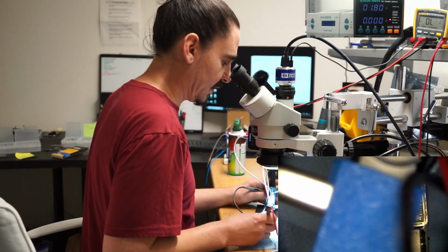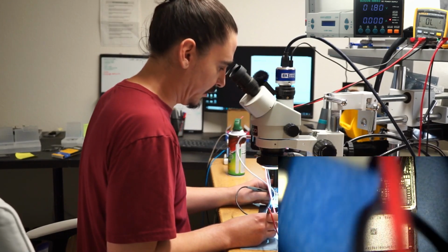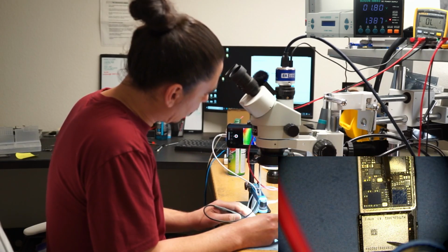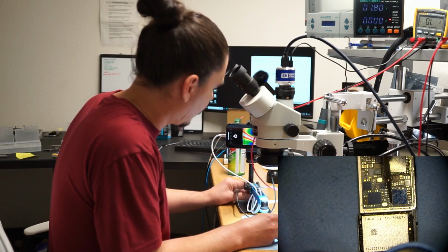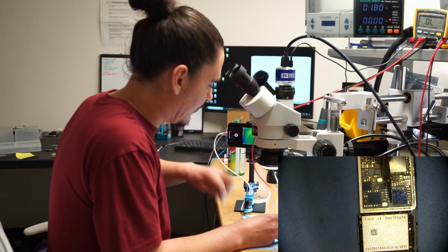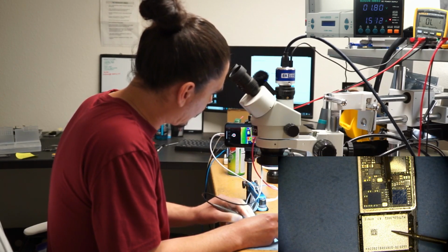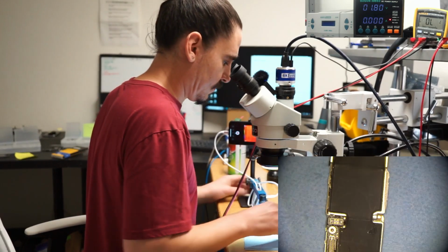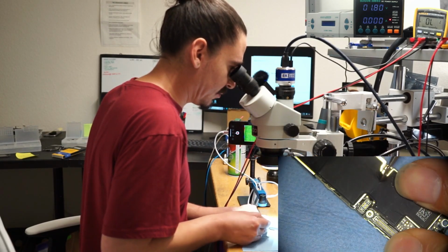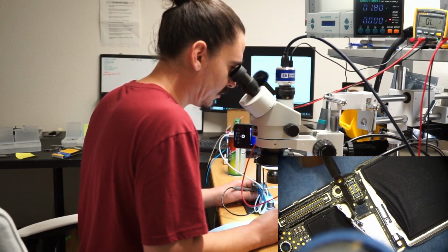So I have a few more spots I can check, and then I'll pull the shield over the CPU and see if it's possibly RAM after that. I was really hoping this was just going to be the Hydra chip, the charging IC, because that would have been the easiest thing to change. I have another charging chip right down here, so I'll check that as well. I can inject into this small cap right here.